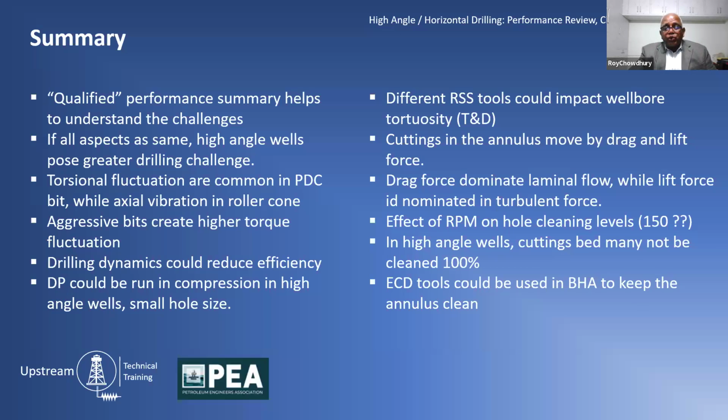Different casing running programs give you a different kind of burst and collapse pressure. One of the very popular programs is that you are dictated by the burst and collapse, but the only way to deal with it is you compare your burst and collapse against the casing that you are running. And if you have a torque and drag issue, then use slightly better or heavier casing at the horizontal section and go lighter on the top.